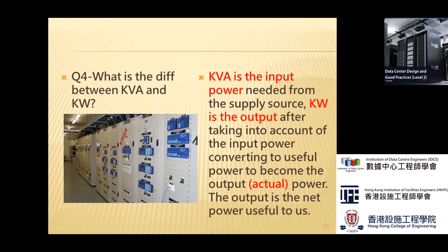You have to make a ratio of 0.9. There's a difference between when you multiply by 0.9 or divide by 0.9. You use kVA times 0.9, for example, and that would give you the output power kW. So that should be quite simple, right? Let's move on.